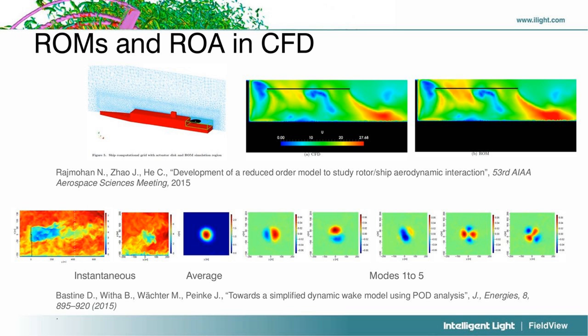Now, what you may already see from the various jargon that I'm using, or if you're familiar with the matter, there's a very large number of modal analysis techniques that can be used, spanning from Fourier transforms, singular value decomposition, proper orthogonal decomposition, dynamic mode decomposition, just to name a few, and each one of them comes in different variants. Each one has a preferred field of application, drawbacks and advantages. So it's really hard at this stage to find out which methods should be applied in general to any CFD simulation.